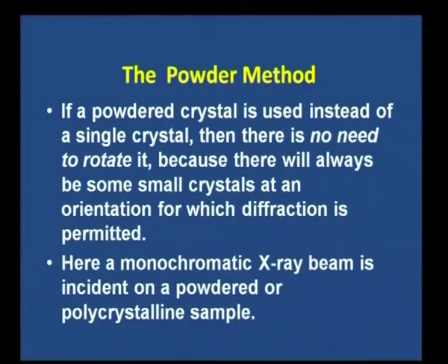The important thing is that there is no need to rotate it, because there will always be certain planes which satisfy Bragg's law. There will be crystals and crystalline planes at an orientation for which diffraction is permitted, that means Bragg's law is satisfied. Here a monochromatic X-ray beam is incident on a powder or polycrystalline sample. This is not a single crystal as in the earlier method. You are using a single wavelength.